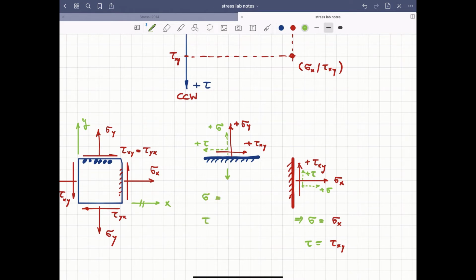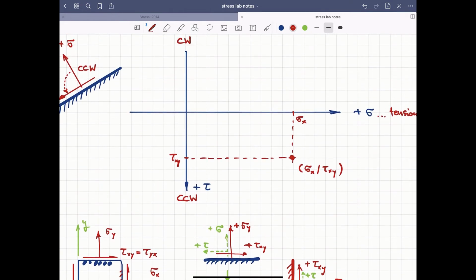So if we compare now, the value normal stress sigma agrees with plus sigma y, but the positive Mohr circle shear stress goes the opposite direction. That means it's minus tau xy. In that diagram, we draw what I marked as green values.